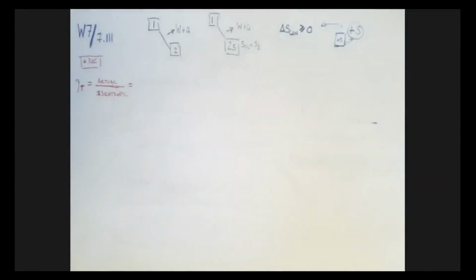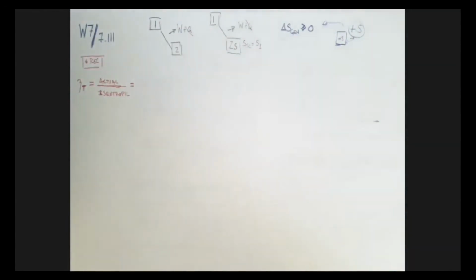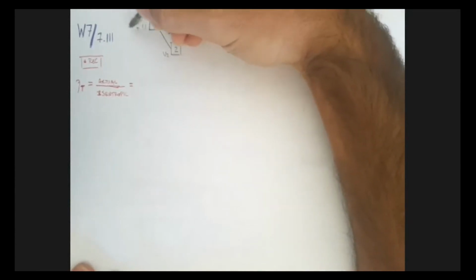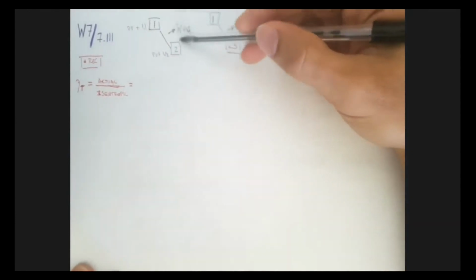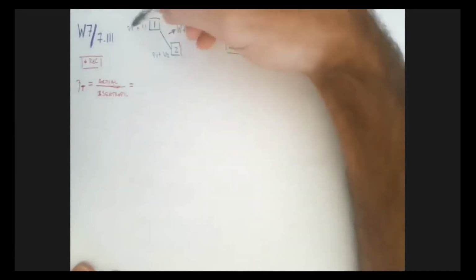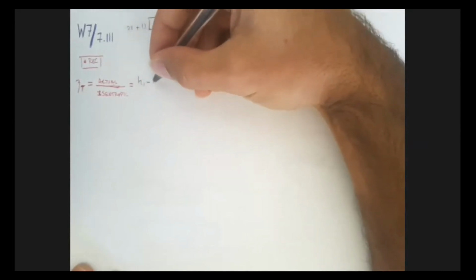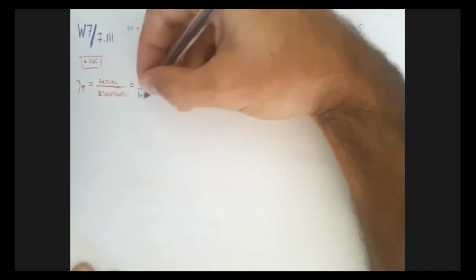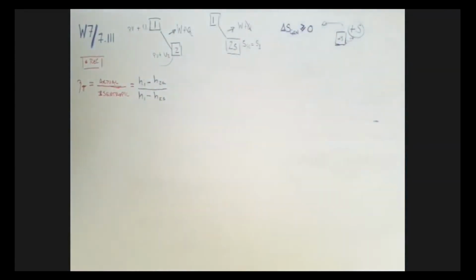Now, there's another way to think of this, because if this is an adiabatic system, we know that this term goes away. There's no Q whatsoever. So all the difference in work, due to the energy difference from U1 to U2, plus, because this is a fluid, the delta PV term, is given in the form of work. We can think of this as the difference in entropy: the entropy 1 minus the entropy of our actual state, 2A for 2 actual, over the change in entropy if this were an ideal case, a completely reversible